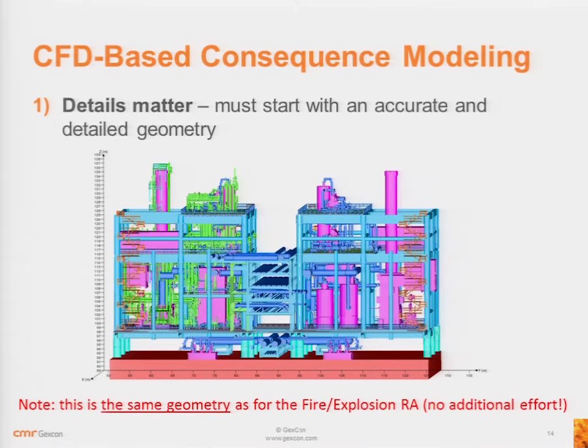Particularly in the early design phase, your CAD model is going to be fairly limited. You'll have big structures, big vessels. You can run a study here, whether explosion risk analysis or cryogenic risk analysis. You will get some results. They're not going to be good results for you. They're not going to be useful because your facility, when it's done, is going to look like this. It will have a lot more stuff in there.